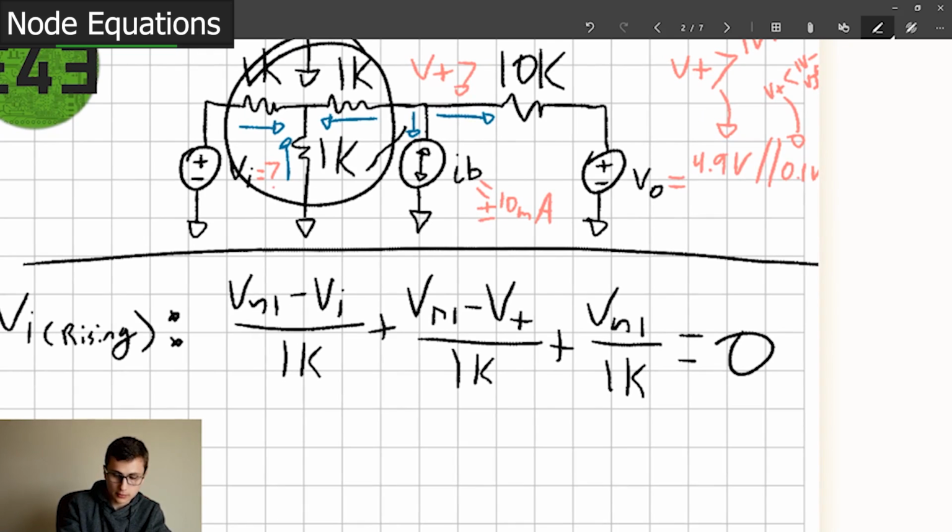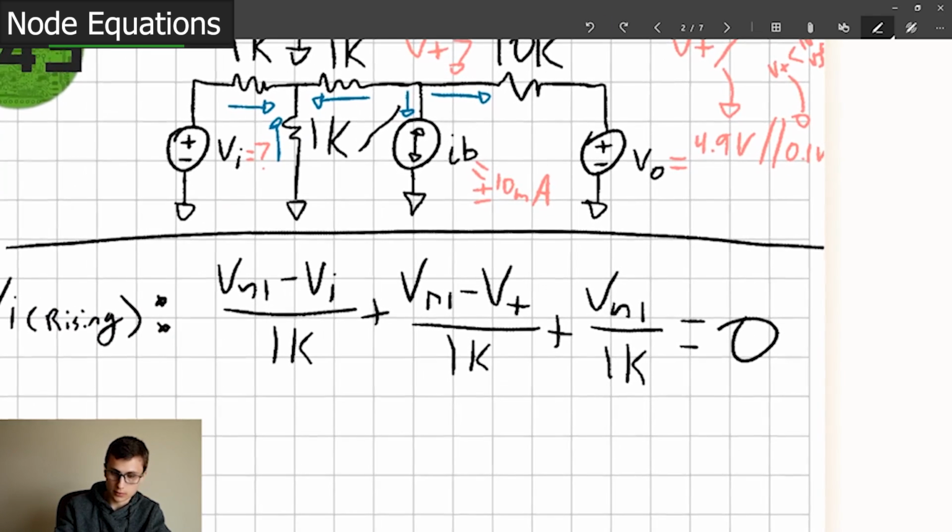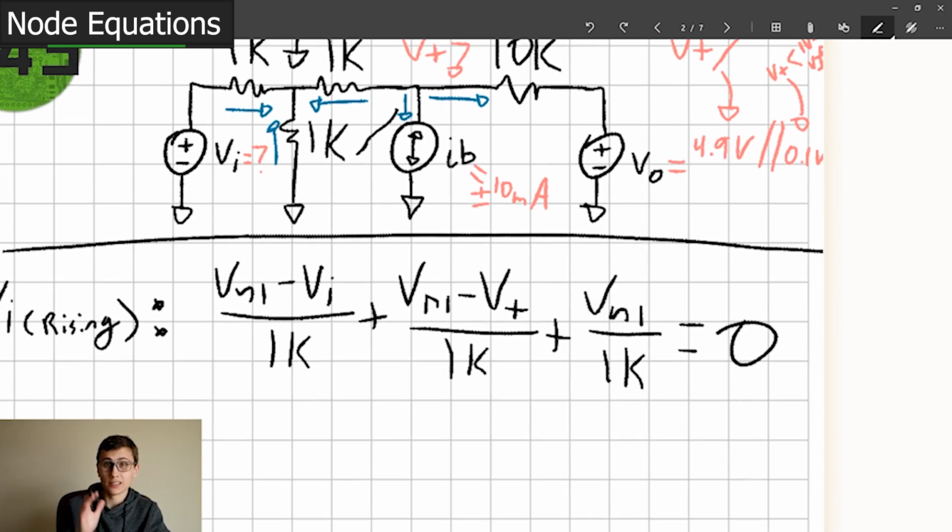Now we've got the opposite, so V_node1, opposite direction. There we go. So now we're going to be doing these three. The tip of the arrow, the point of the arrow, is the term that we're putting first in these equations. That's what we've decided to do. Again, it's important that you stay consistent. It's not important which way you do it, because if you're inconsistent, you'll probably end up with the right answer, but with the opposite sign, and you'll feel pretty silly. You also might get the wrong answer and the wrong sign. So be careful.